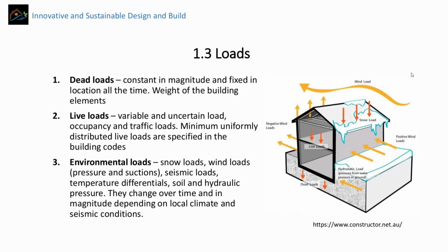And then we have environmental loads. For example, we have snow loads and wind loads. Wind loads could be pressure and suction. We might have seismic loads where buildings and infrastructures are located in seismic regions. And temperature differentials are also loads.